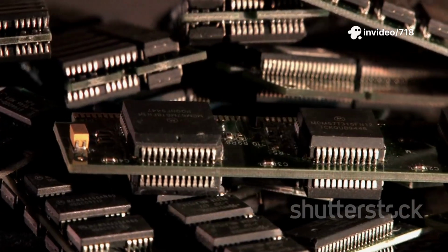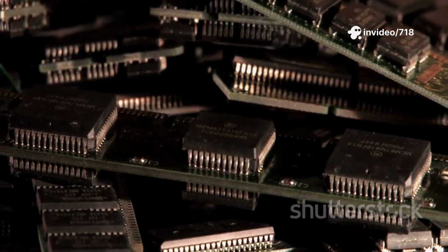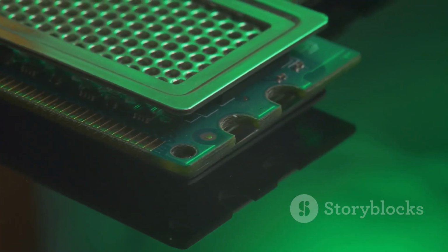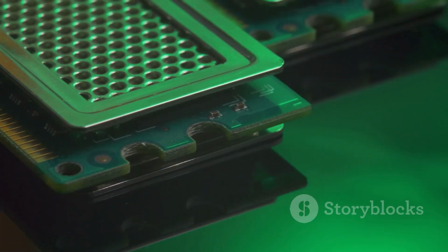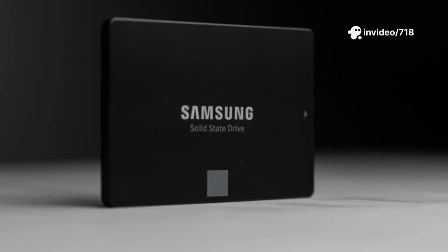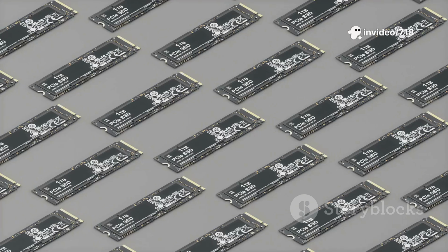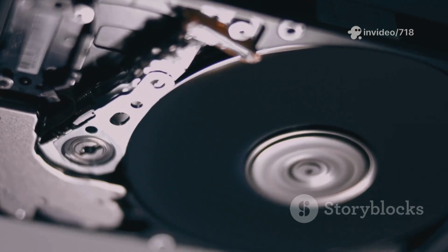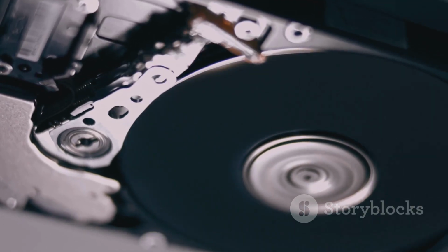This mechanism is incredibly robust for long-term storage, but it has its own set of trade-offs when it comes to performance. The primary trade-off is speed and endurance. The process of forcing electrons into and out of the floating gate is much slower than simply charging or discharging a DRAM capacitor. While modern SSDs are incredibly fast compared to old hard drives, their read and write speeds are still significantly slower than DRAM. Writing to flash memory is particularly slow.